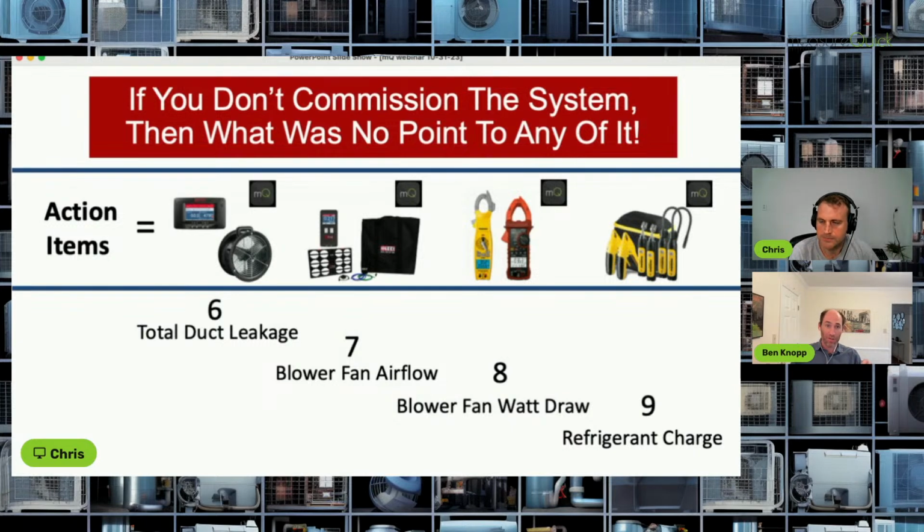And this is a special piece of equipment that we use. This is a cold climate heat pump with flash injection. When it gets really cold outside, that thing just works harder. And because of that, the heating capacity of this heat pump is much, much greater than its cooling capacity, which is fantastic for our climate because we can design to the cooling load and still get most of the heating load covered by the heat pump at much higher efficiency.